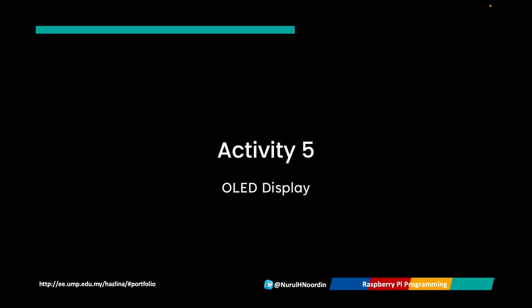Download the SSD1306.py file from a trusted source like GitHub, in which you can do so via the UMP STEM Lab GitHub. Open Thonny IDE and connect to Raspberry Pi Pico. Copy the SSD1306.py file into the Raspberry Pi Pico file system. Import the library in your Python script using import SSD1306. Once installed, this library allows us to send commands to the OLED display using simple functions like text, show, and fill.